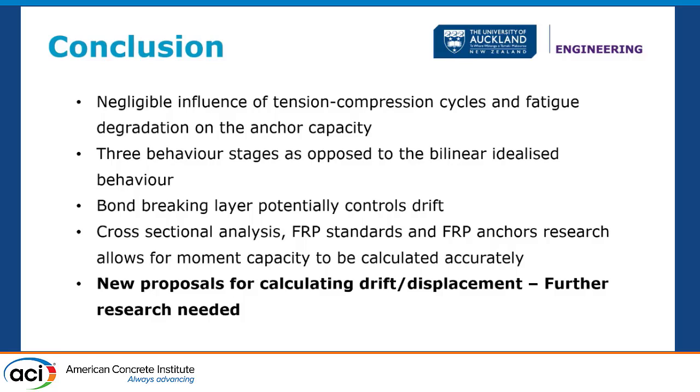So in conclusion, there is no difference with the tension-compression cycle, there is no fatigue degradation, there is no effect of the confinement. Why do I know that? Because test 2 and test 3, which were more or less a repeat, have the same numbers, and I could predict the moment capacity very well. So that means we are not compromising the strength of the anchor because of that cycle. We have that 3-stage behavior that we have seen in many other applications as well.